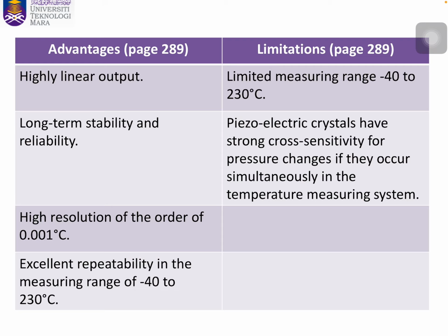Next, what are the advantages of piezoelectric? It has highly linear input, long-term stability and reliability, and high resolution of the order of 0.001 degrees Celsius. It also has excellent repeatability in the measuring range of -40 to 230 degrees Celsius.